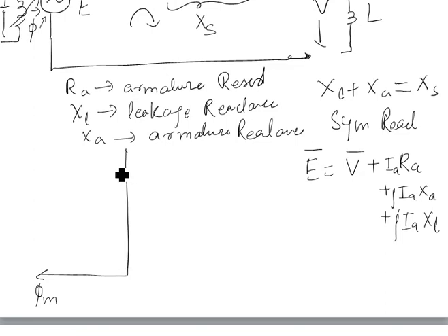Now what happens is that there is an inductive load, so no doubt V is lagging, this is my V, and there is one more lagging quantity, that is IA. Since it is an RL load, there will be some phase angle, that is phi. And this is your delta. So delta is actually the angle between E and V.